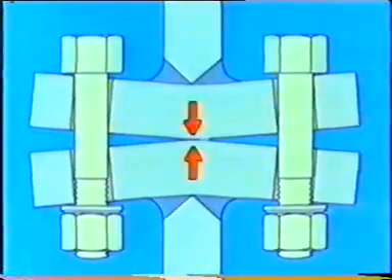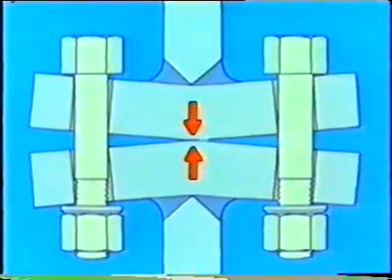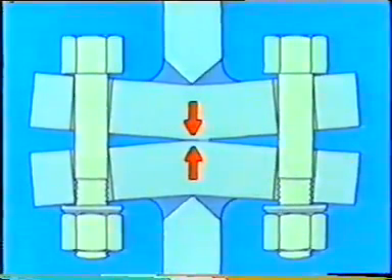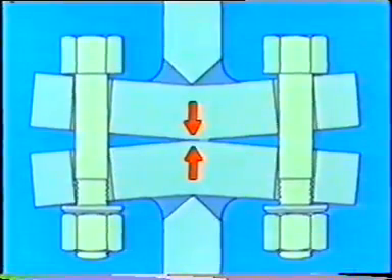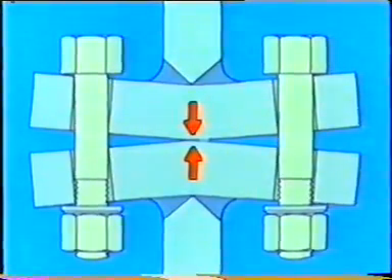If flanges have become curved due to welding, this concept also applies. The contact surface is automatically located in the center of the connection. From a fatigue point of view, a favorable situation.